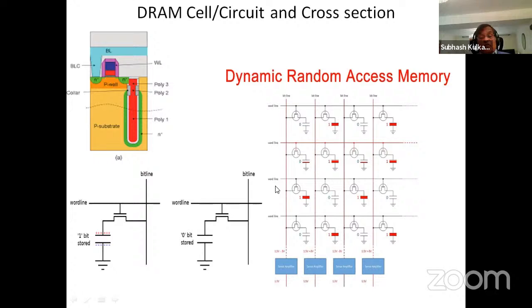So what they do is, this word line, this is an array of transistors. You apply the word line, so voltage is turned on. And now you are going to read which transistors have state 1 and which transistors have 0. Basically, when the bit line is turned on and you keep that voltage on, it starts bleeding into these devices, especially if it is a 0, this capacitor will start getting charged. So this voltage goes down.